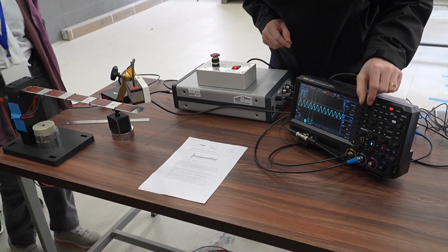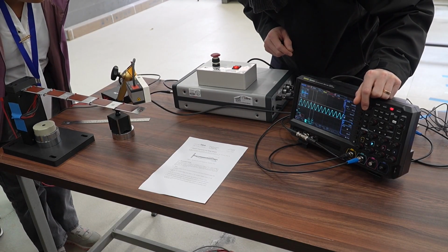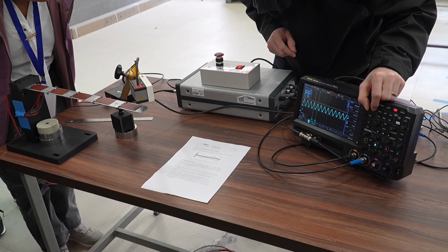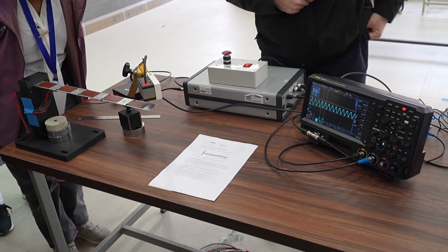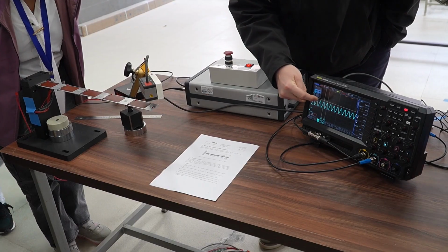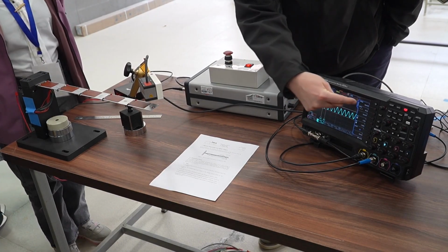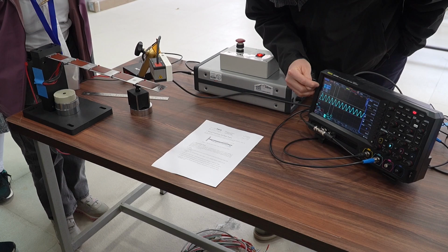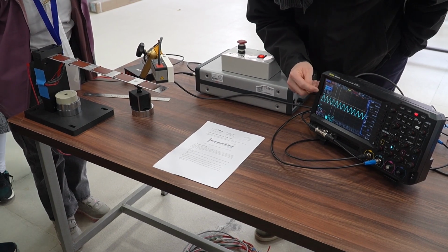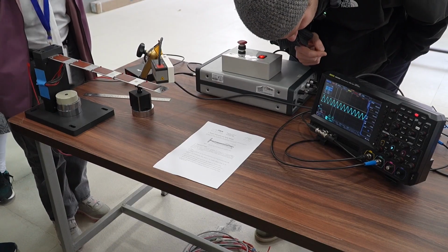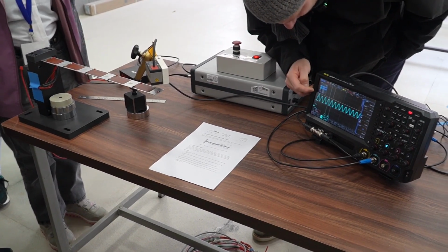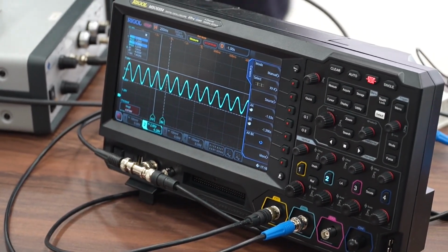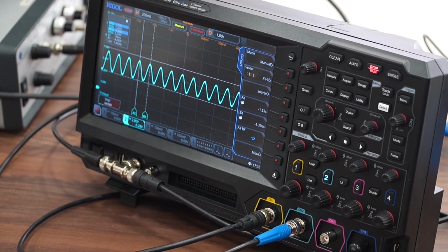And now if I do like this, I can shift the cursors to the peaks. Now the two cursors are on two peaks. If I want to increase the quality of that measurement, I take not one peak but several peaks and divide by the number of peaks, because then the accuracy increases, obviously. And then here I can already read that the delta x, so the delta in time, is 1.134 milliseconds, and that translates to 7.462 Hertz. So the first eigenfrequency is about 7.5 Hertz.